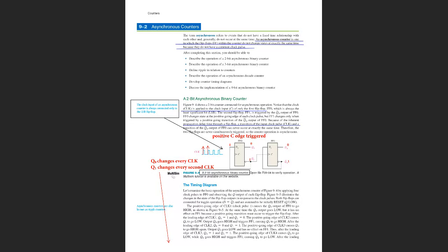And as you may see, if we have initial state Q0 = 0, therefore not Q0 is 1, and this one is fed back to D0, and when the clock comes with its positive slope, obviously the next state will be 1, because this is how the D flip-flop works, and the output not Q0 will be 0, which is now at the input.